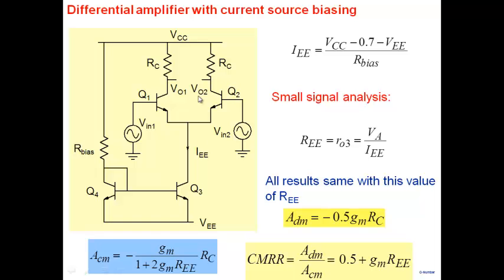Now in all of this, what we are doing is that when you are implementing a transistor on an IC, I made the statement earlier, the cheapest and the easiest to fabricate components are the transistors. Resistors are difficult to make. They occupy more area. And capacitors are impossible to make unless they are very small value. So the general trend in making IC amplifiers is what? Use as many transistors as possible. Don't use resistors and avoid capacitors.